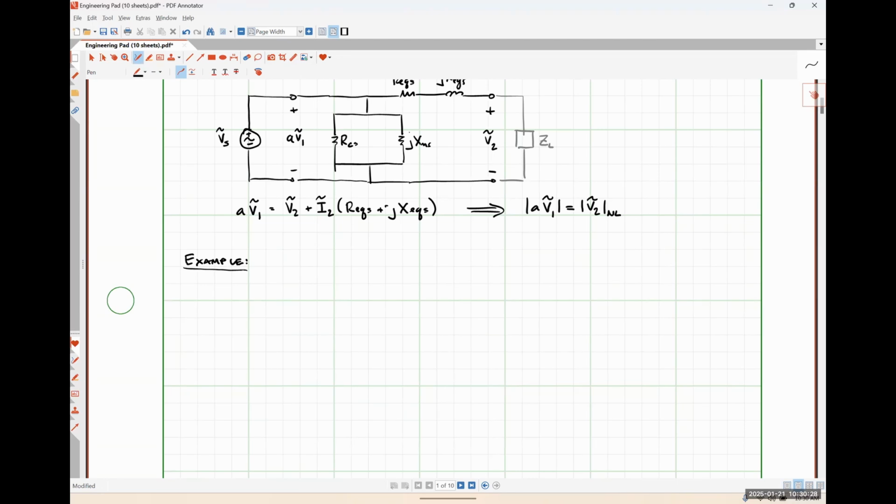So all of the power and distribution transformers that are in service can be either a step up or a step down transformer, depending on how you're connecting things, okay? Now, there's nothing stopping you from connecting a lower voltage on the side with less turns, and then getting a higher voltage on the side with more turns, right?